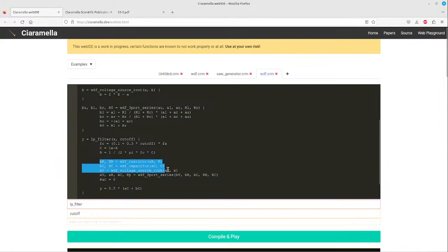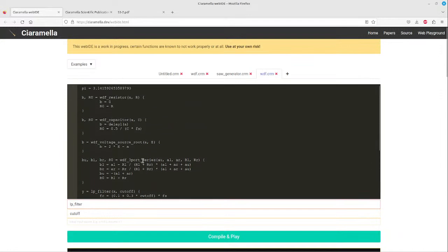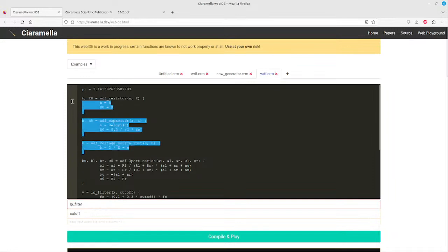If you just look at this, you can find delay-free loops, no? But the compiler expands these composite blocks and finds the hidden delays inside the capacitor, for example. And this is very modular, because you can easily reuse the blocks you are coding here. Essentially, the compiler doesn't work on hierarchies or levels, but flattens everything and then deals with the whole graph, taking care of all operations at the same time.